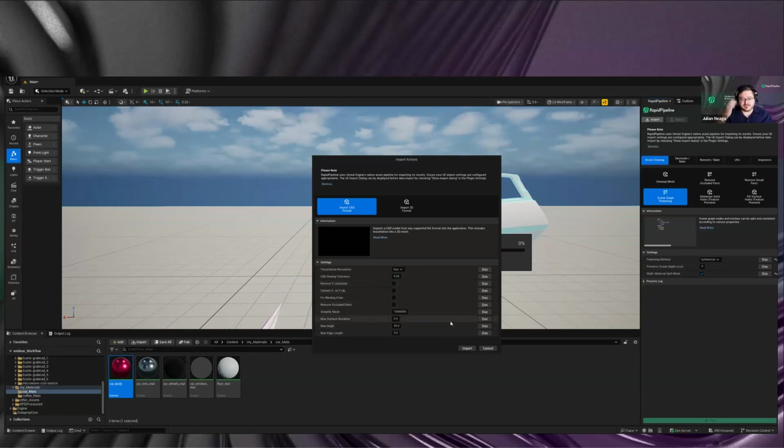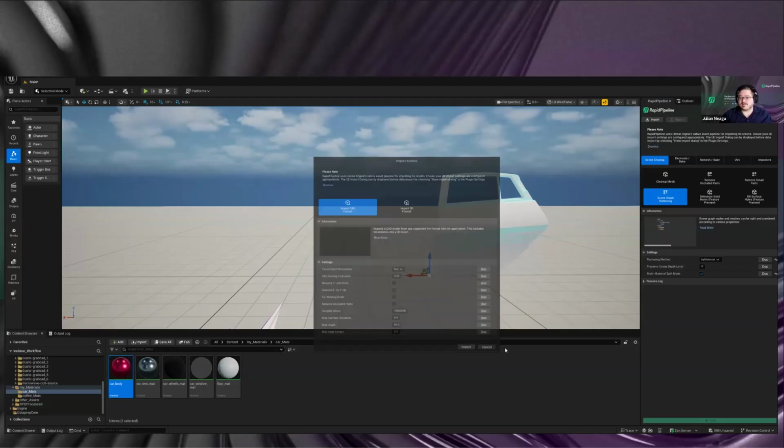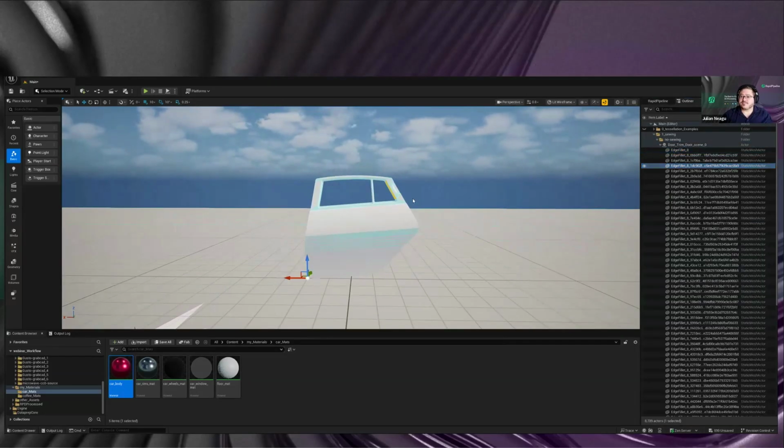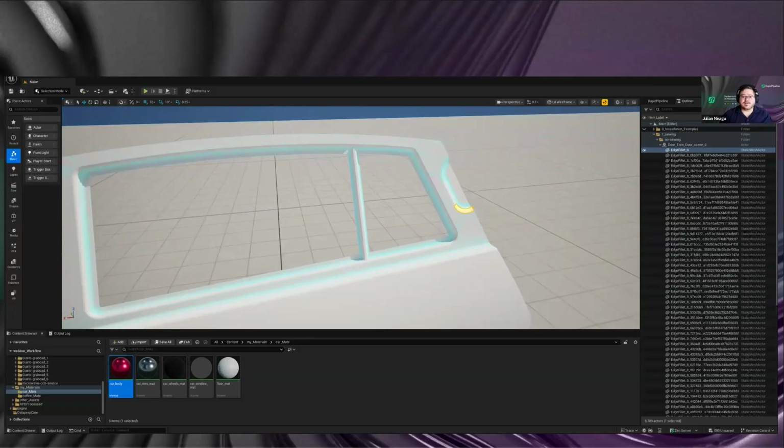Yeah, so that can be very helpful, specifically also with some of the automotive assets where you would have a lot of single small patches, and this is a nightmare to decimate or optimize or even process in terms of settings in anything further. Let me see. In this example, we have a door file with no sewing, so you can see exactly what I mean by patches.